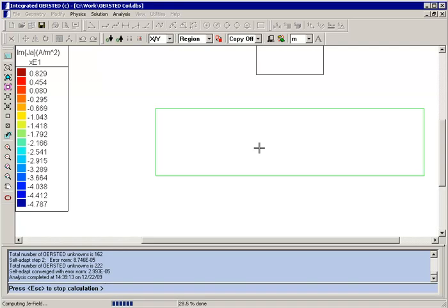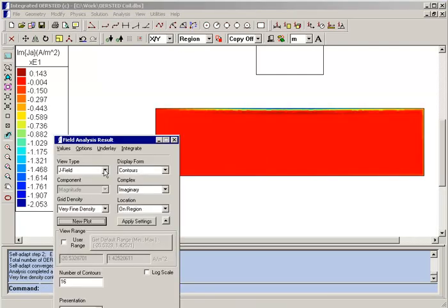However, they will be concentrated much closer to the surface than with the copper because the skin effect will be much smaller at the same frequency due to the permeability of the steel. If we go back and look at a field line plot,